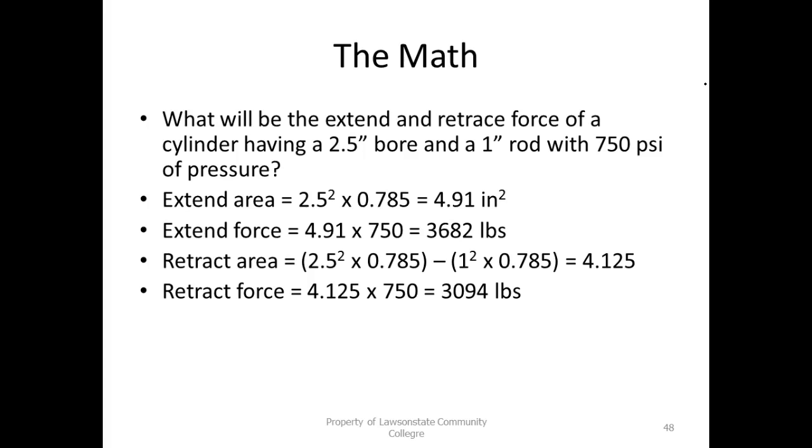So what's it going to do? It throws it out, and it gets in everything. So that's a big problem we have. Condensation. Also, we get condensation because anytime you compress something, it heats up, right? You understand that? And then when it cools down, it's going to do what? It's going to condense too. But then we have the problem that when you compress it, it can't hold the water anymore anyway.